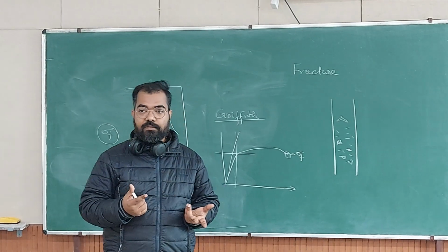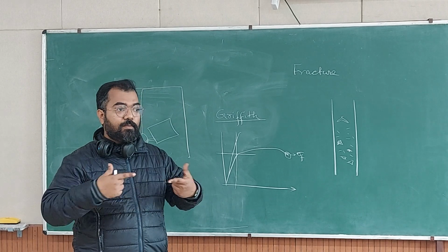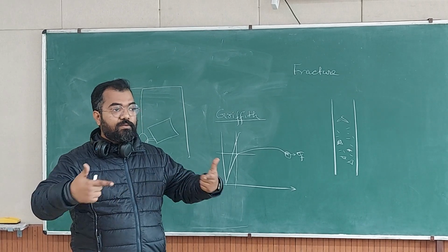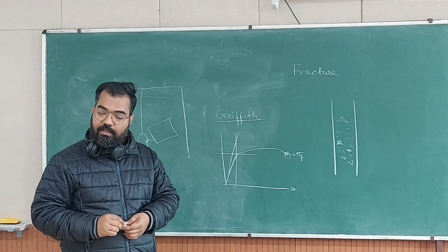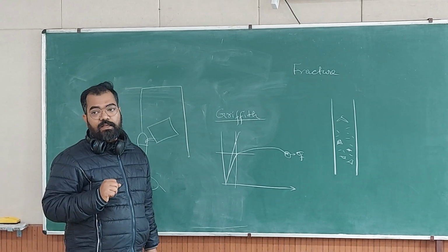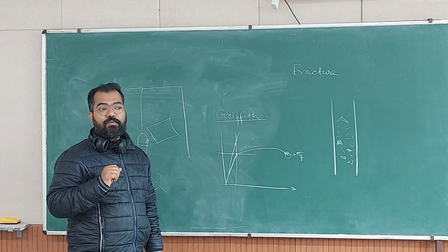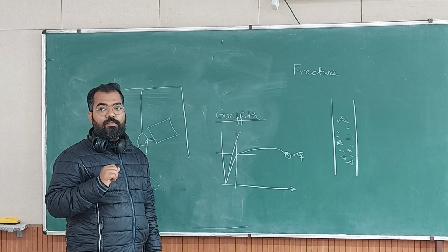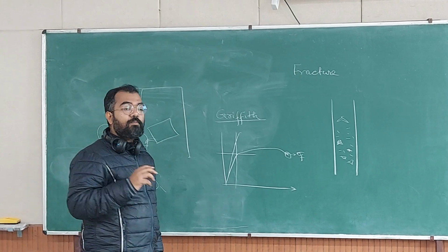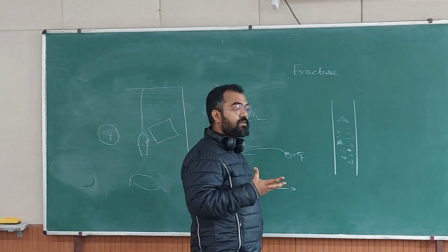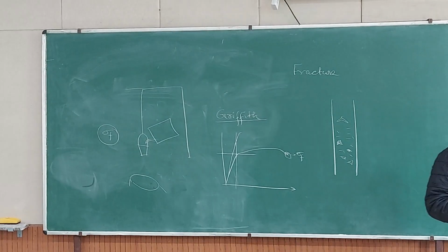Maybe two of the micro cracks will join and become bigger, they will propagate more, and then the material will break. Now tell me why different sizes are giving different stress values. Greater the size, more the breaks. Yes. So you have more cleavage initiators or stress raisers if you increase the diameter of the sample.